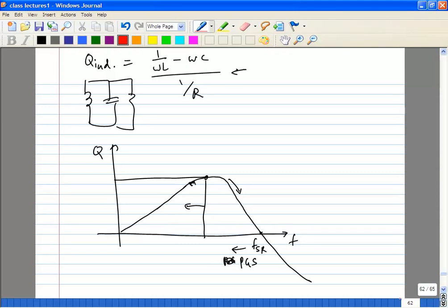So earlier when people used to work with discrete components, the distances and other things were large enough such that they were comparable to the wavelength, maybe several orders higher than the wavelength of the signals you work with. Whereas now we have reached a point where on an IC, the connection between, let's say, a transistor and this inductor, or the next amplifier stage, is much shorter than the wavelength of the signal you are working with. So that means you don't have to consider distributive effects.